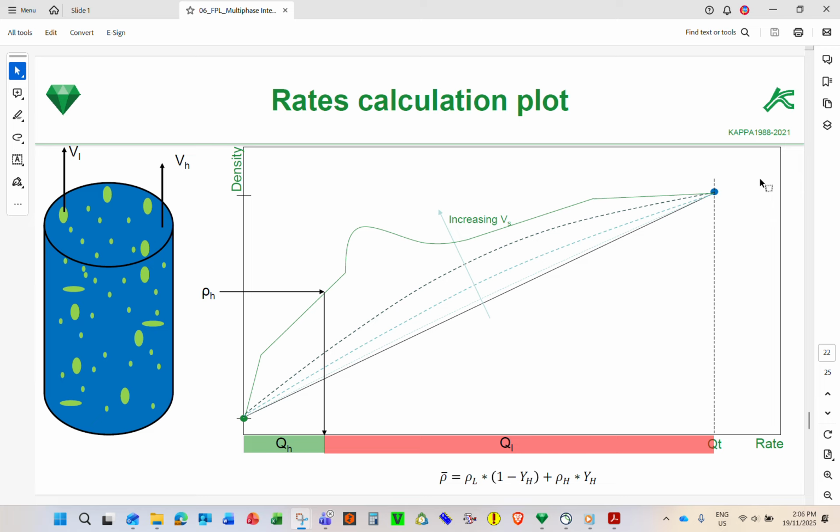It's calculated, you have P and Q, water Q or gas Q. You might have density from the two, and this is density calculated from the holdup. If you have holdup, you have rho from PVT and holdup from capacitance, you get the density and you can put that one in.